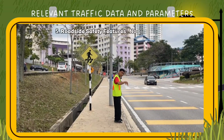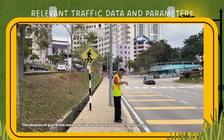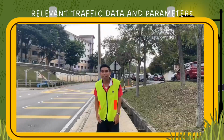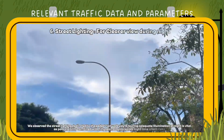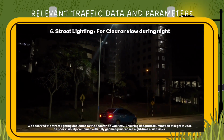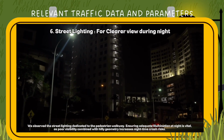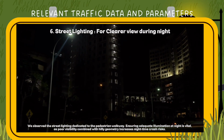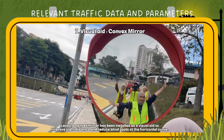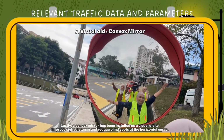Fifth, roadside safety features, no guardrails. The absence of guardrails increases the risk of severe crashes, particularly if a vehicle leaves the roadway. Sixth, street lighting for a clear view at night. We observe the street lighting dedicated to the pedestrian walkway. Ensuring adequate illumination at night is vital, as poor visibility combined with a hilly geometry increases the nighttime crash risk. Seventh, visual aid, convex mirror. Lastly, a convex mirror has been installed as a visual aid to improve sight distance and reduce blind spots at the horizontal curve.